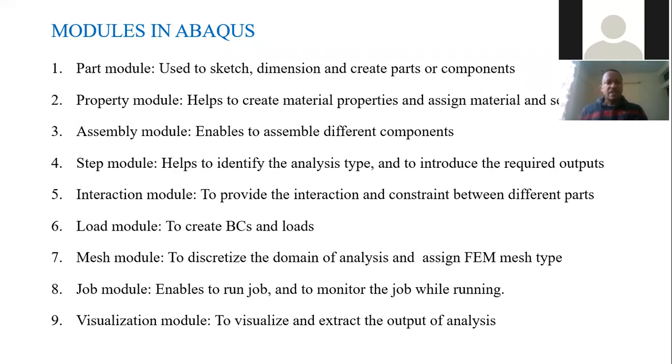The step module helps us to identify the analysis type and to introduce the required outputs. The analysis output will be given through the step module. And the interaction module will help us to make interaction between two connecting parts which come in contact. Okay, so the interaction module also helps us to constrain some parts. Next, the load module. The load module helps us to create boundary conditions and to create different loads.